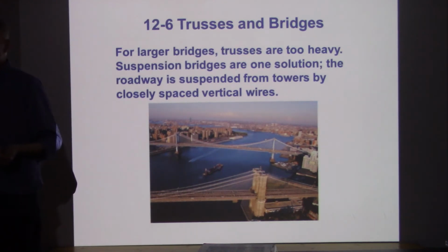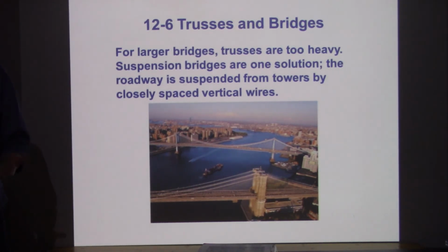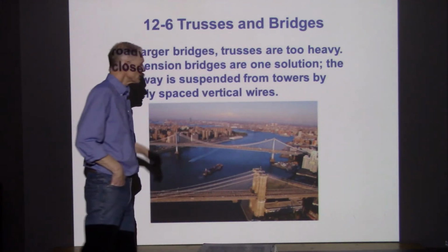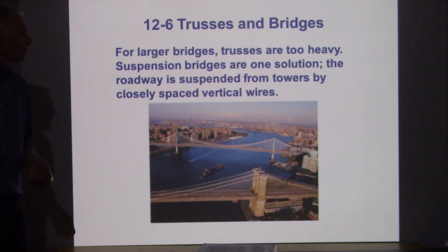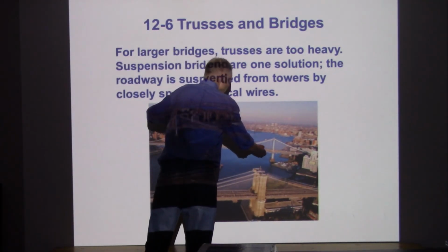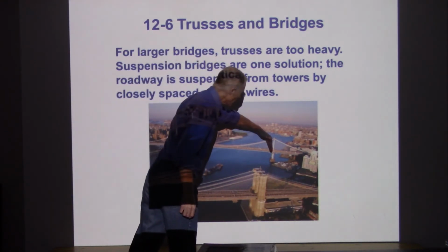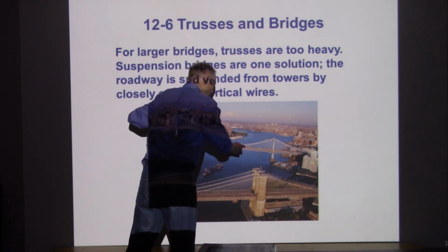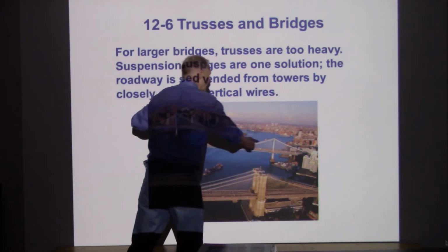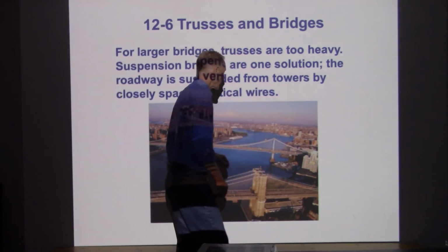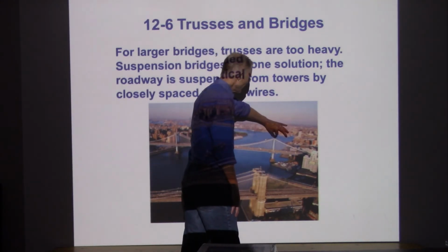Between the towers. So if you search construction on some of these bridges, a few years ago there was an anniversary of the Bay Bridge and then an anniversary of the Golden Gate Bridge, and there are great videos and photos of the construction process, seeing the steps that they went through. So you start hanging all these cables. Now the cables are designed not to be under compression, right? I can't have a cable that's under compression. So the towers get built, cables get hung, and then the roadway is being supported by these individual cables, which are also under tension. So the roadway is being supported by tension in all these cables. The tension of all of those is transferred to these arching cables, and then the force is downwards on the towers. So the tops of those towers are supporting all of the weight of the roadway that's been transferred through the cabling up to this point right here.